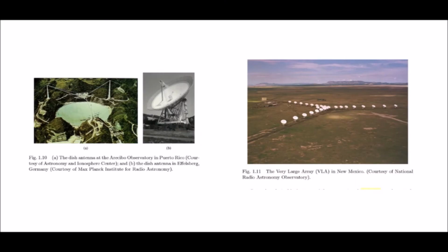Another method of obtaining high-gain antennas is to use a parabolic reflector, with the feed antenna at the focus. The antenna is also known as a dish. For a given frequency, the gain is proportional to the diameter of the dish. In theory, the gain can be made as high as one wishes by increasing the dish diameter.